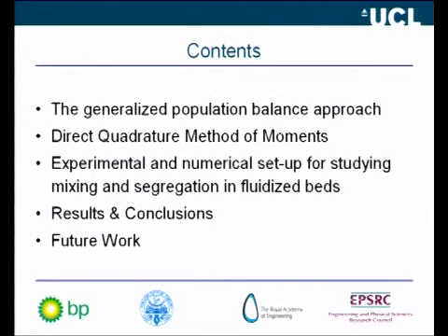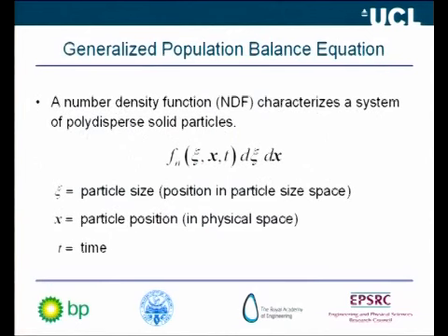First of all, I'm going to give a short introduction to the generalized population balance equation. After, I'm going to briefly introduce the direct quadrature method of moments that we use to solve the population balance equation within computational fluid dynamics codes. After, I'm going to explain the experimental and numerical setup that we used for studying mixing, and also segregation in fluidized beds, using the QMOM and DQMOM. And after, I'll present the results, some conclusions and the future work.